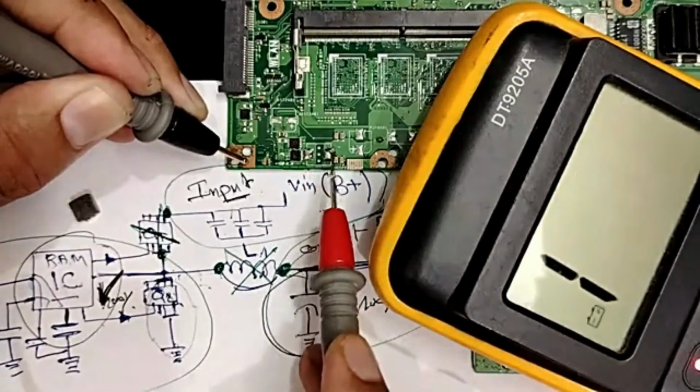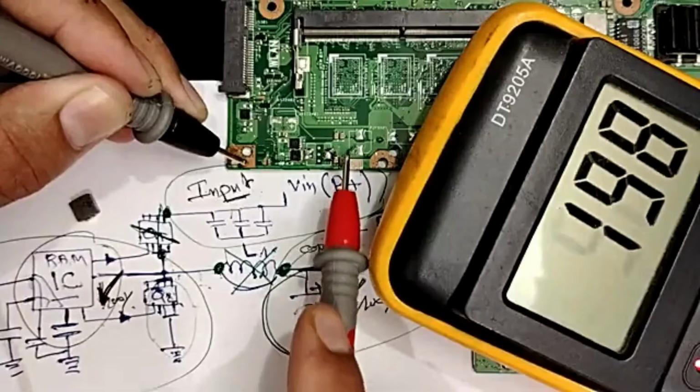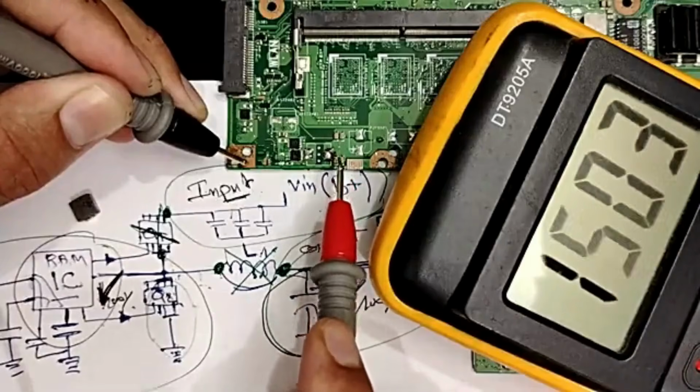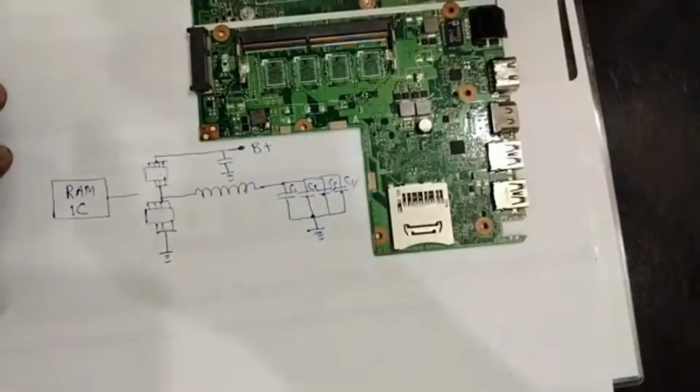Means one of the ceramic capacitors is shorted. Why? Because we don't have an electrolytic capacitor. One of these guys is the shorted component. Very simple. Just stay tuned, my friends.